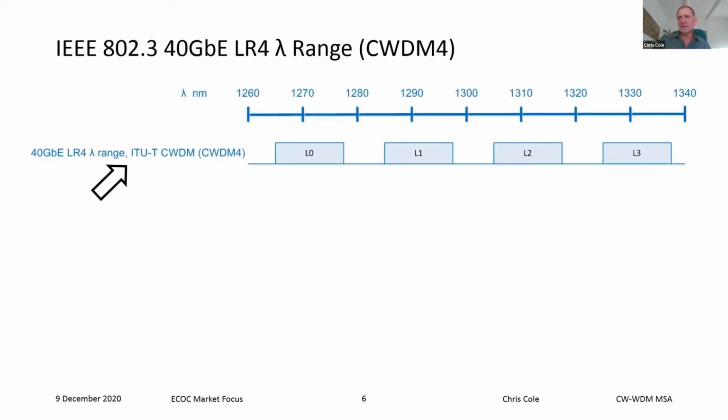Okay, let's move into something substantive. So let's review the high volume grids that the industry has used. I'm showing here a subset of O-band. I'm only going out to 1340. O-band goes somewhat further to longer wavelengths. And this is drawn so it spans the first WDM high volume Datacom grid. There was an LX4 grid which preceded that, which has a larger span, but that really didn't hit high volume.